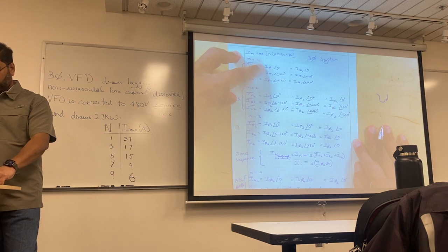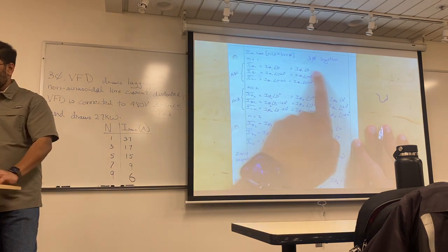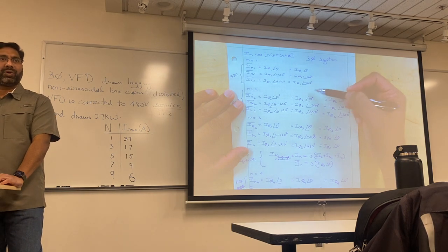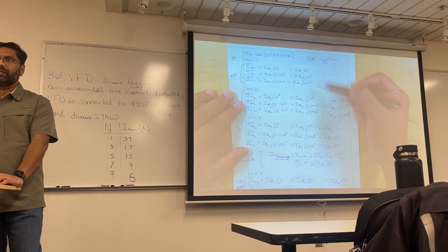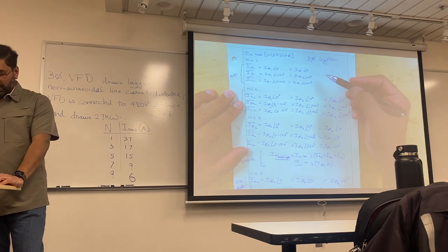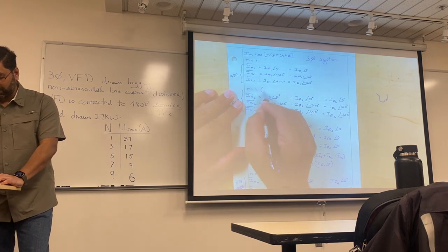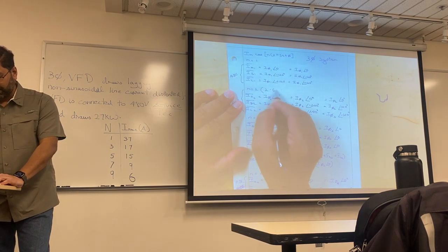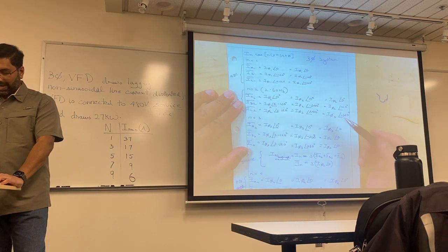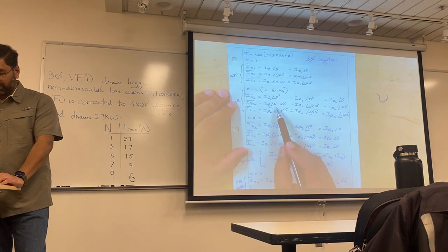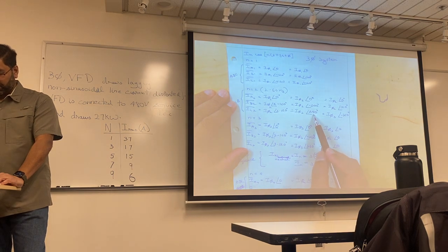It's IA, IB, IC, and these are the three angles associated with it: 0, -120, and 120. At this point, is there any confusion with at least these angles? No. All right. I then put in my second harmonic, which would be 2 times 60 Hertz is what I'm trying to show here. And I end up with the 0 remaining 0, the -120 becoming -240, and 2 times 120 becoming positive 240.